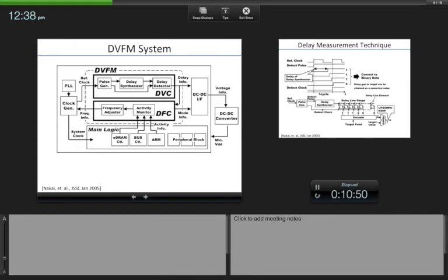Then you have a processor. Here they are using an ARM processor. So again, is the processor in an idle state or a non-idle state? So like that, you can keep track of, there will be one enable signal from each of these, which you feed into a counter. So activity monitor is nothing but a counter. So over that phase of observation, you count how many cycles were these things active. And based on that, you adjust the frequency of operation for the next phase. The way you adjust the frequency is set up the clock generator to generate now the target frequency.